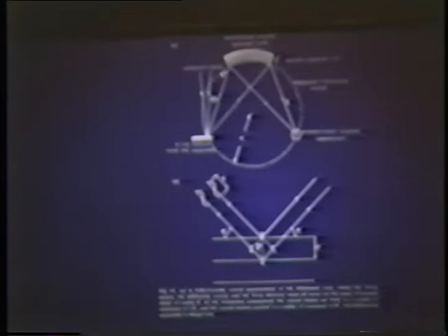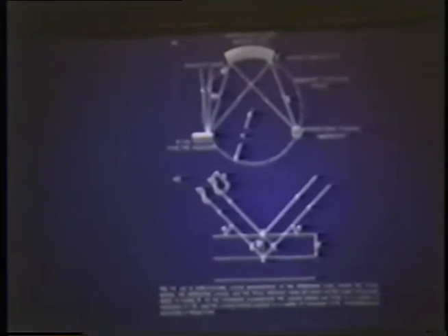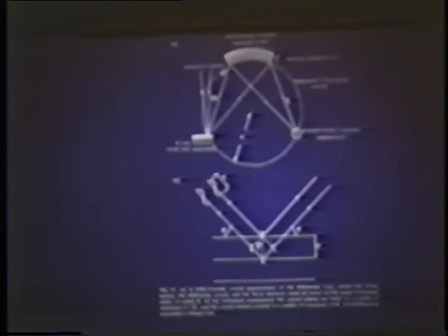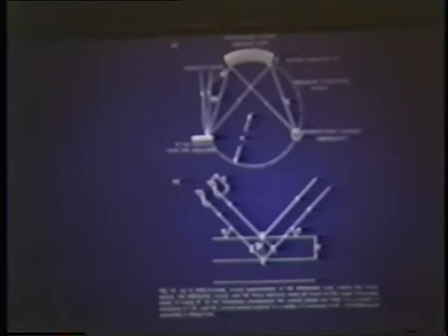Now, these X-rays come off as a wavelength, and this is why these are called wavelength detected. The X-ray resolution is excellent, and is equivalent to something between 1 and 10 electron volts, which eliminates many of the problems associated with the characteristic peak identification and overlap, which I will come to later. There is a direct relationship between the wavelength and the energy of X-rays. It is given simply by a formula that I have put in the proceedings, where the energy in keV times the wavelength in angstroms equals 12.396. But you can actually convert X-ray energy to wavelength quite easily.